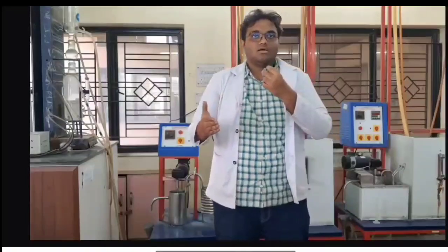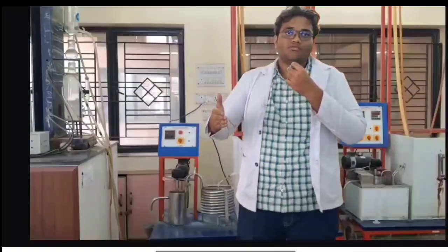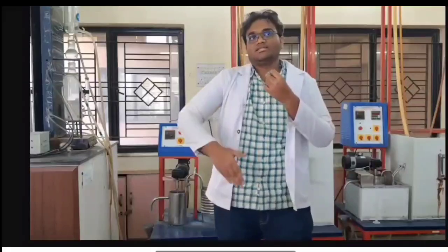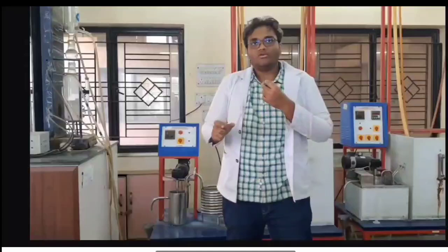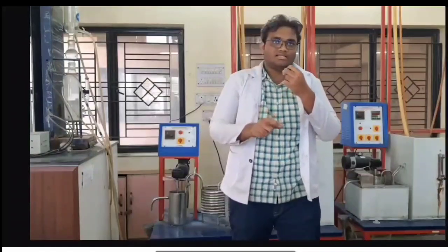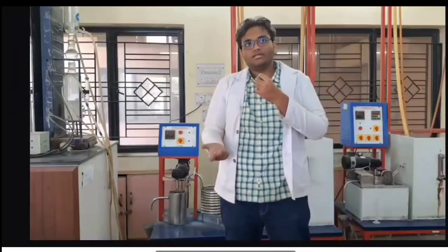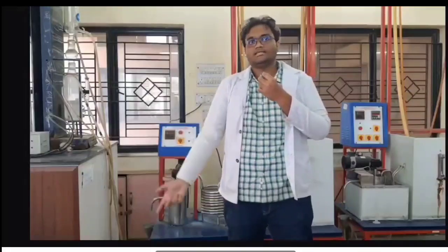Now, cut to a close up of the titration process, which will explain the color change. The next crucial step is to record the volume of NaOH used for future calculations, as it will allow us to determine the conversion rate in the CSTR.